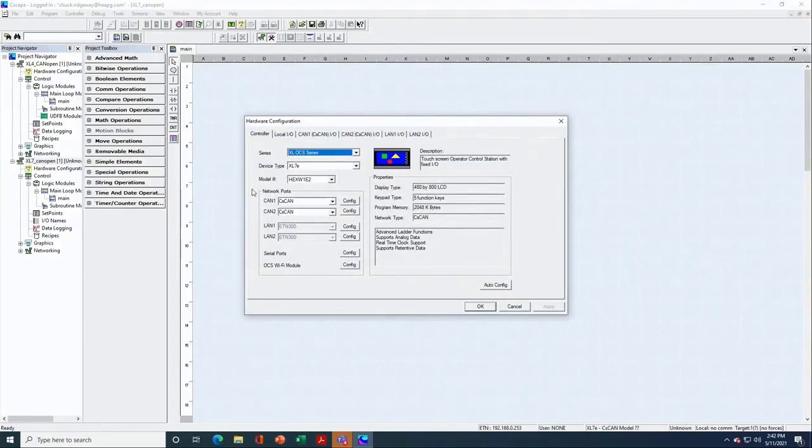Now in the case of the XL7, I don't need to do any kind of firmware update to the XL7 because the XL7 has 2 CAN ports, and the second port is selectable for CANopen. Now my first port, you'll see a CANopen choice there, but trust me, select CSCAN on port 1 and CANopen on port 2. Now what is that CANopen option on port 1? What in the world is that? Well, we do have the ability, only with the XL7, for you to have CANopen support on both CAN1 and CAN2, but that's really rare.